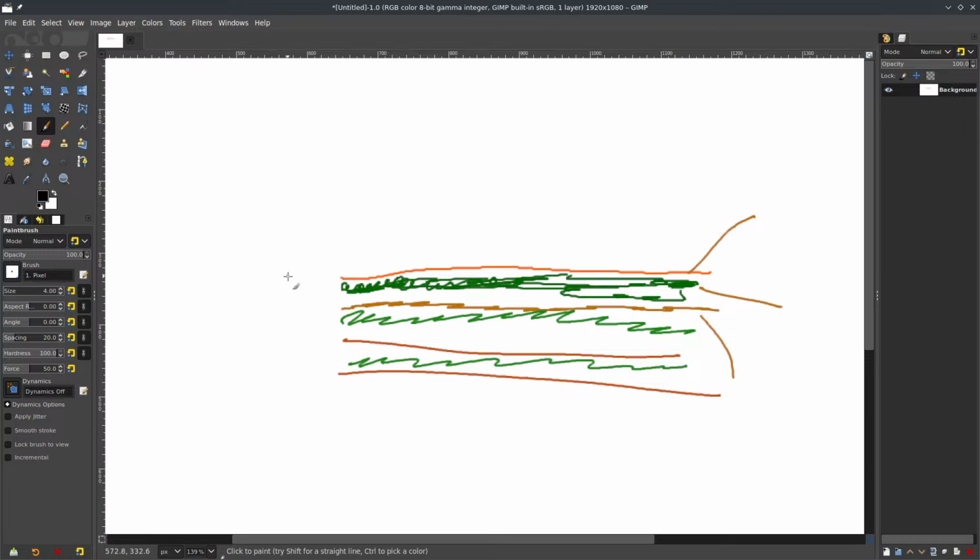JLC PCB, which is where we're going to order from, has a standard, and they're going to tell you what it is, and they do it for such a low cost. Unless you do their advanced option, you can't specify these, but we should tell KiCad what they are. That's how thick is this layer of copper, how thick is this layer of substrate, how thick is this layer of copper here, how thick is this substrate throughout.